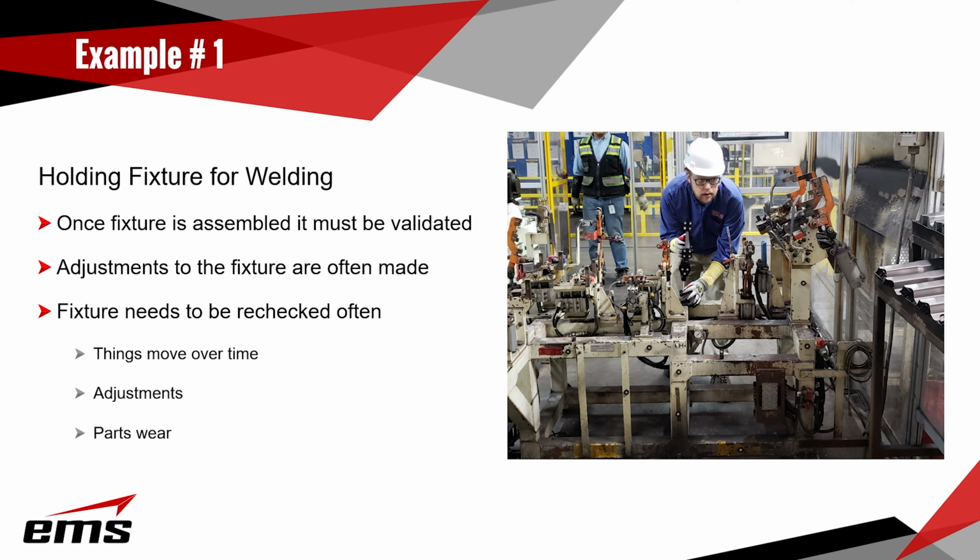because if they're not validated, the part may not be held in the correct position, and then when you go and weld them together, a series of parts, you may go assemble it in the car and it doesn't fit right. So you've got to make sure your fixture is correct to begin with.